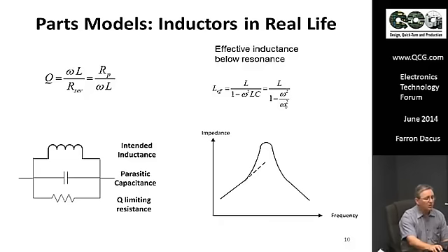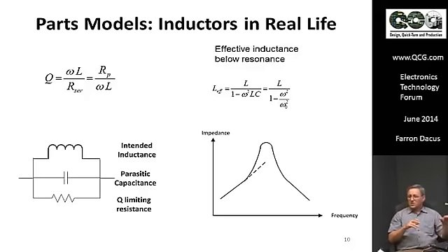Well, we can do some simple math again to show that effective inductance is once again larger than the rated inductance, and that's something that has to be taken into account in anything where you're using a signal inductor, not a choke, but a signal inductor for filtering, for a tank in a VCO, anything like that. These things have to go in your simulator. An S-parameter simulator may let you put in self-resonance or Q directly, and it'll run that model internally. But if you're using, say, SPICE, then you have to put that exact model in, or even something a little more sophisticated for some parts.